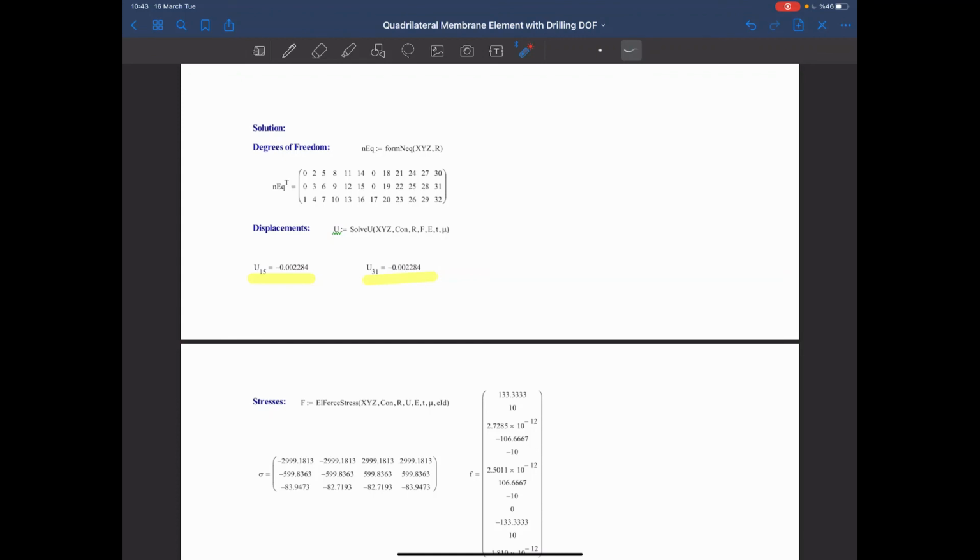In order to see the shear variation within the depth of the member, remember that we expect a variation like that. I should mesh it with more elements. If I use a single element with respect to the depth of the member, I see a constant shear strain not corrected with the area.